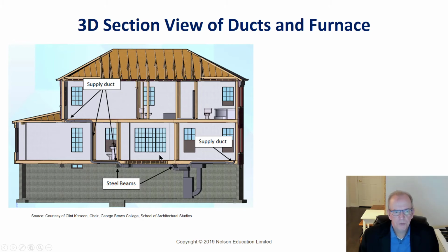So this is using a BIM drawing, just giving you a basic concept of how that can be showing where the actual duct layouts are. And we can clearly see, you know, we got to get around the steel beams. So that's got to go around at this point. It's got to go up. It's got to go inside the joist over at this point where the joist changes direction. So there's those kind of considerations that goes on. Usually if ducts are going to be below the ceiling, like I said, you try to do it in the basement. And then if you have issues up above, that's where it's going to require a bulkhead or something similar.